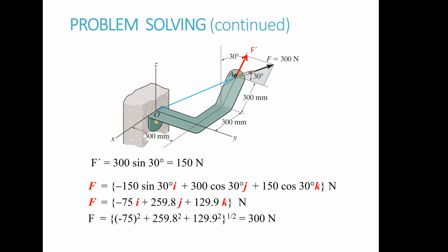All right, so now you have this. Here's our force vector, here's the magnitude of that force vector, and we want to find out how much of it is going off in the x direction, and how much is going in the z direction. We're doing these two first. If we look at it from this F prime's perspective, this is right along the x-axis, parallel to the x-axis, at least in that plane, right?